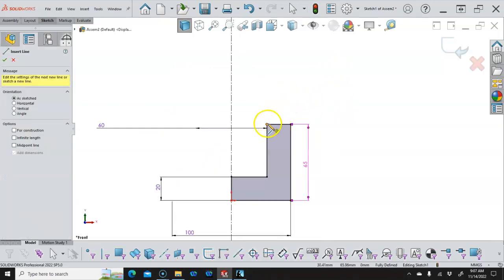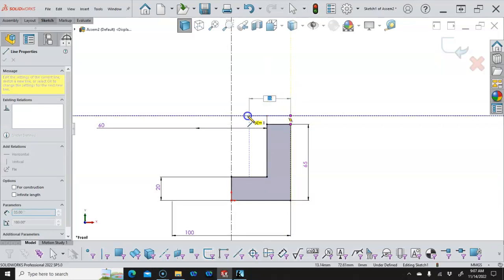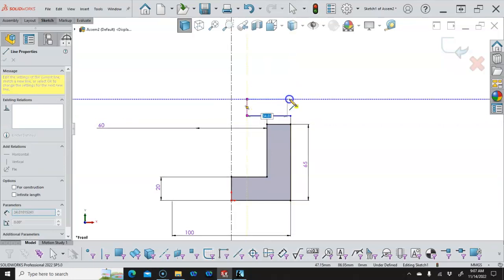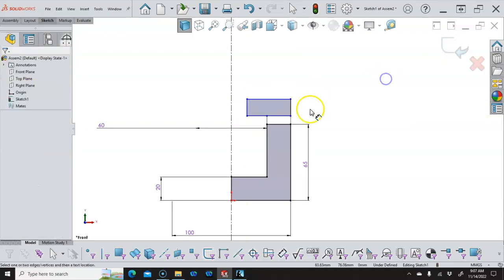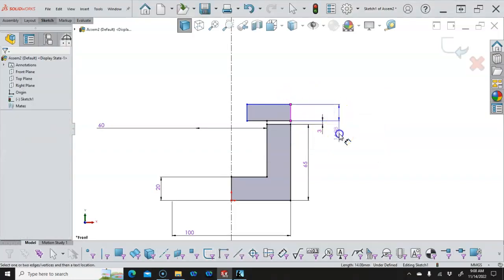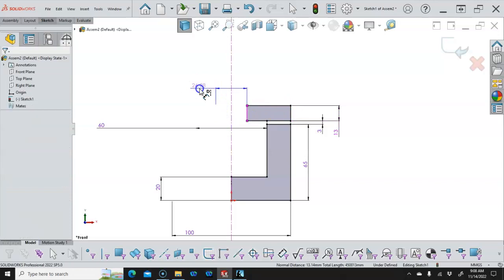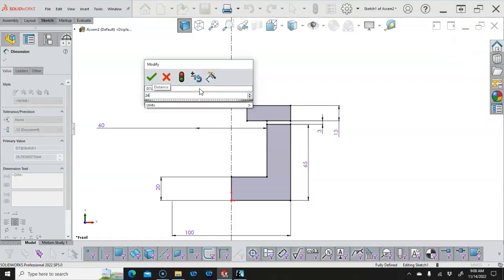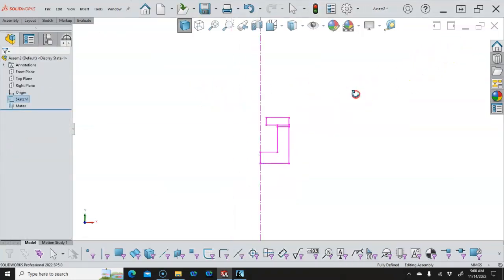All right, so line for the gasket, and then we'll stop a little bit short and complete the rectangle. All right, so we have a height of 3 millimeters for the gasket, a height of 13 millimeters for the lid, and then the minor diameter of the M24 will be 24 minus 3, so 21 millimeters. And then we go ahead and accept.